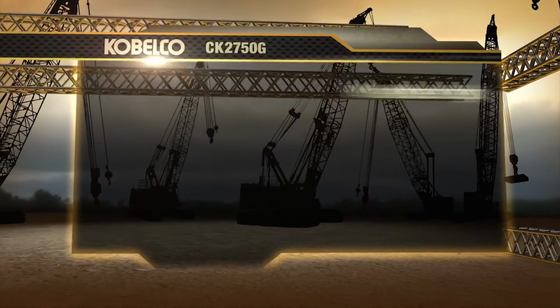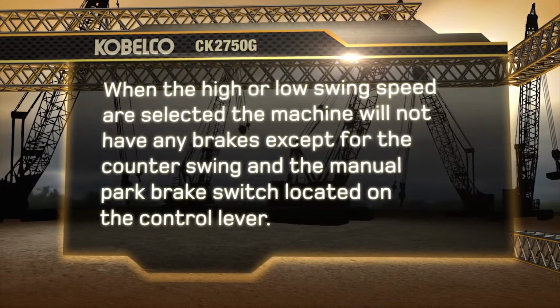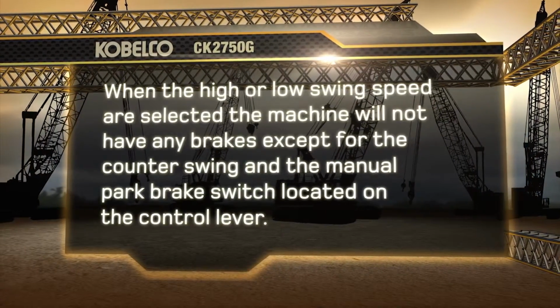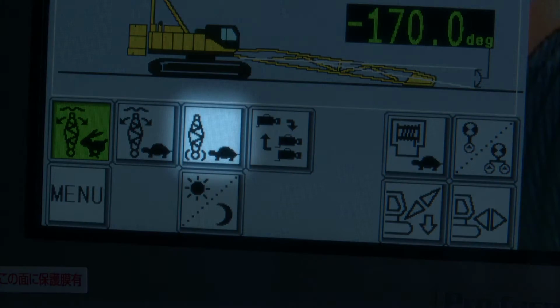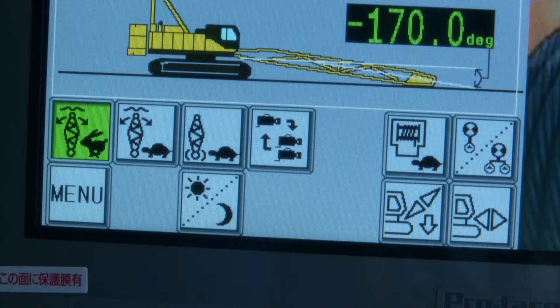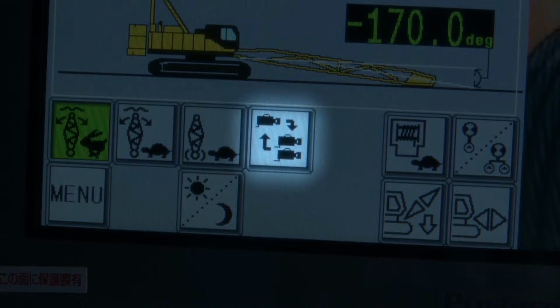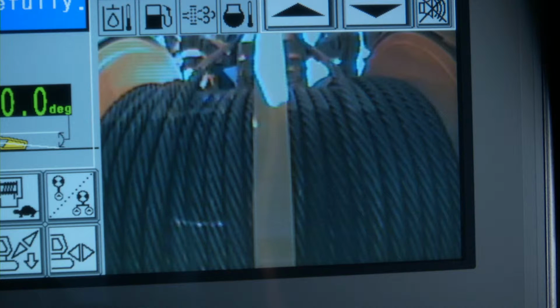When the high or low swing speed are selected, the machine will not have any brakes except for the counter swing and the manual park brake switch located on the control lever. And the third icon is the swing brake. In low speed swing, this setting provides 50% braking in 1.5 seconds after the swing lever has been in the neutral position. The following icon is for the drum boom camera. Touching this will turn the lower right portion of the LMI screen to the boom winch camera.